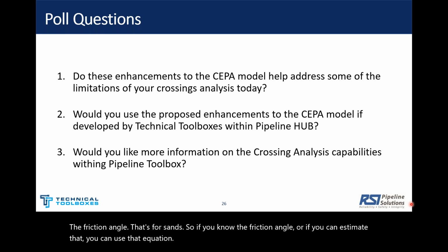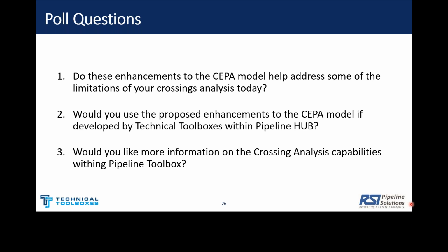Okay, this will be the last question, just as I know we're 10 minutes over, and frankly, we could go for another half an hour here with the amount of questions we've gotten. So regarding cover and its effect, for the same soil type, if the pipe is newly installed, can it be assumed that the effect of the protection from cover would be different from if the pipe has been buried for over 40 years, as the soil may be much more stiff? And if so, can this be accounted for in the calculations?